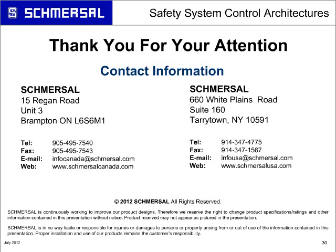So when you look at that decision tree we showed in the beginning slide, what you saw was a chart on severity, frequency, and avoidance, and it got us into a performance level. But your first step in achieving that performance level is figuring out what control architecture, what your design of your safety system is going to be, because certain performance levels require a minimum of a certain control category.